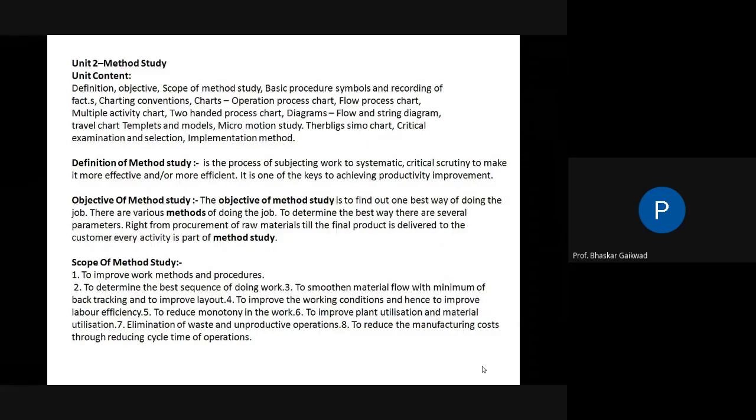Very simple thing is that while doing any job on a lathe machine, turning, facing, chamfering. Correct. So while making these jobs, while facing, you can go for chamfers. No need to keep a separate operation for chamfering. So in this way, unnecessary operations we can reduce. While facing, you can give the chamfers. Correct. Not necessary to make a separate operation for chamfering.